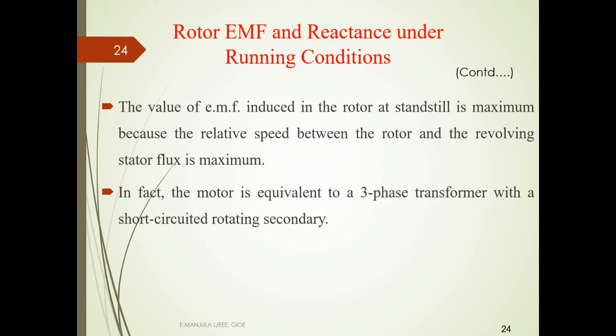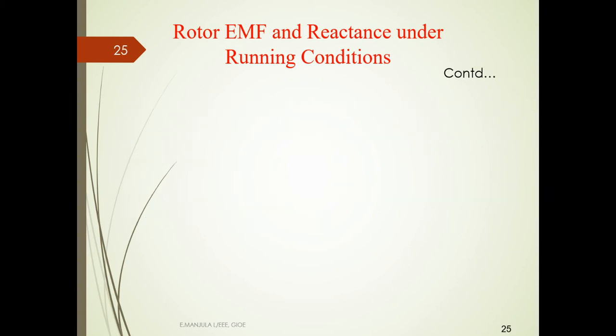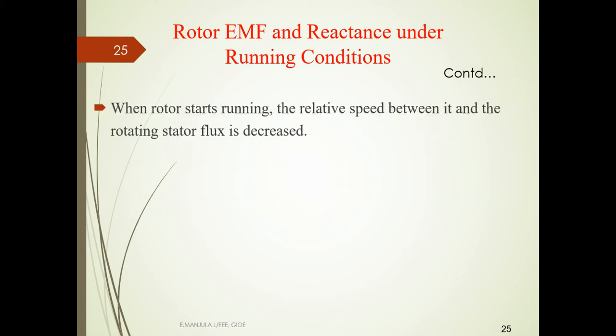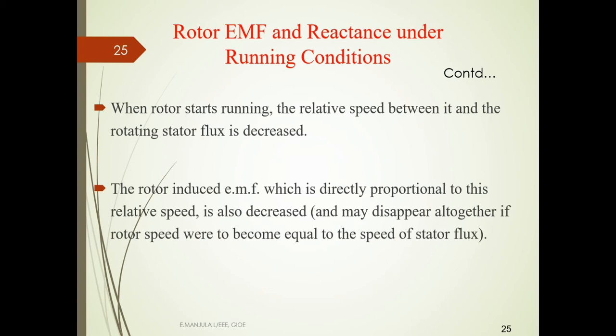In fact, the rotor is equivalent to a three-phase transformer with a short-circuited rotor secondary. So we have discussed even this. When the rotor starts running, the relative speed between it and the rotating stator flux decreases. Then the rotor induced EMF, which is directly proportional to the relative speed, also decreases.